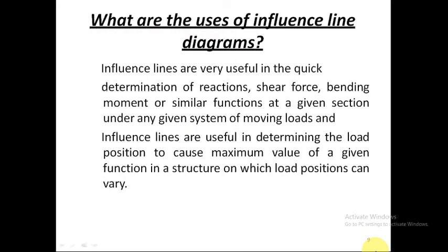Next, what are the uses of influence lines? After the rolling loads, we will also be discussing influence lines. Why are they required? Influence lines are very useful in quick determination of reactions. Placing the load at any location, you will be able to find out the reactions. Then also the shear force at any point on the beam can be located.